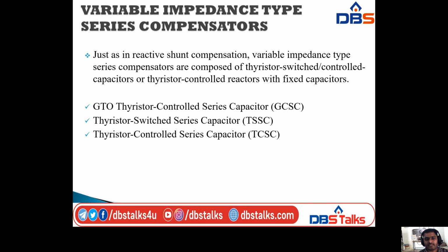Next, coming to the next concept, that is variable impedance step series compensators. Actually in shunt compensators also we have this concept, variable impedance step shunt compensators, and here we have the variable impedance step series compensator concept. This is a very important concept. Just as in reactive shunt compensation in the previous chapter, the variable impedance step series compensators are composed of thyristor switched or controlled capacitors or thyristor controlled reactors with fixed capacitors.